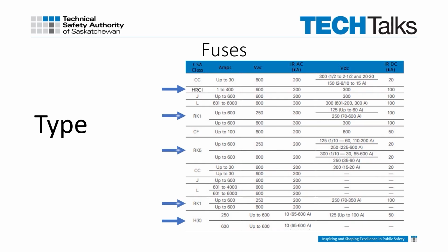Class R are general use current limiting with optional time delay fusing and 200,000 to 300,000 amp interrupt rating. Finally, Class L are non-renewable current limiting time delay fuses which are bolt-in and have 200,000 to 300,000 amp interrupt rating capacity.